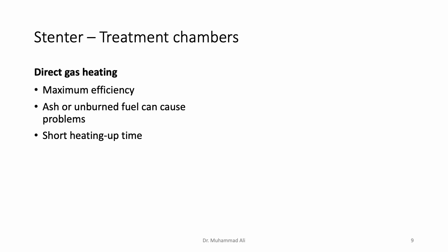This point is related, in a way, to the first point also. In direct gas heating system, the heating up time is very short, right? Or in other words, if you compare it with all other heating systems, then this has the shortest heating up time. Again, because of the fact that as soon as the burners are fired on, the air inside the treatment chambers starts to heat up.